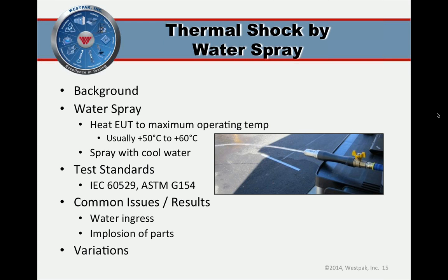As you would expect, common issues and results would be water getting into the product, and that's probably just a function of the water spray, but you can see implosion of parts due to rapid cooling and not having sufficient venting, or things like cracking or other failures, and that's in general due to the thermal shock.